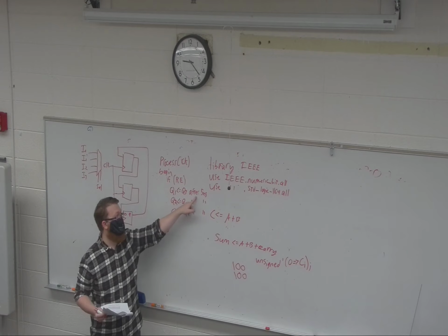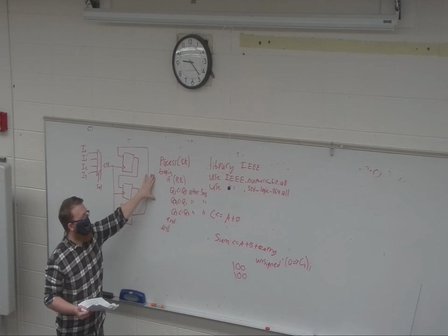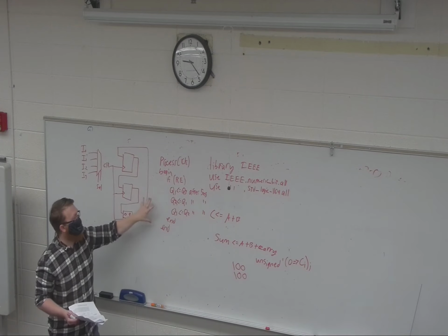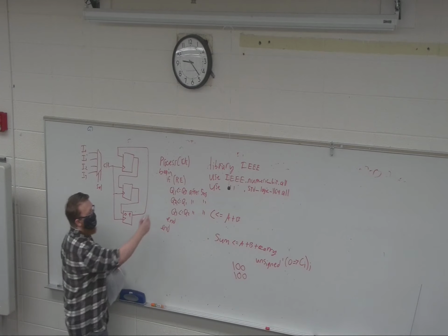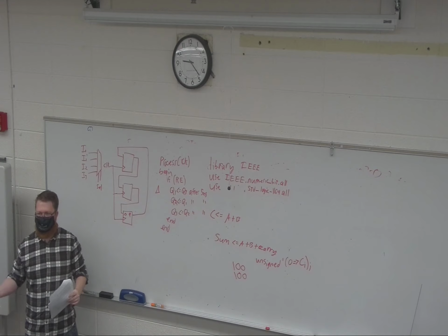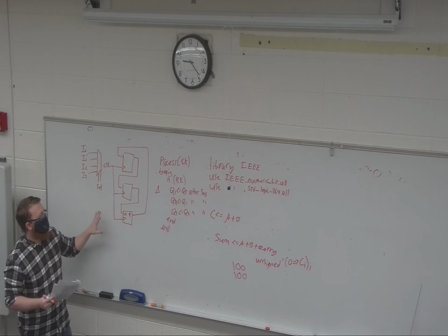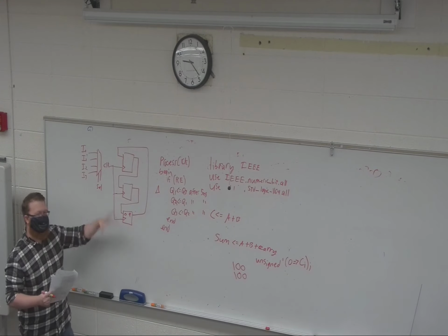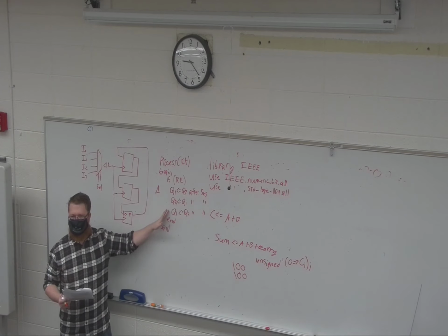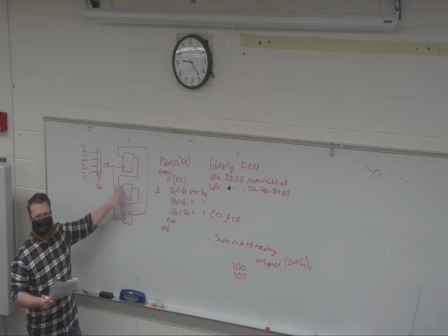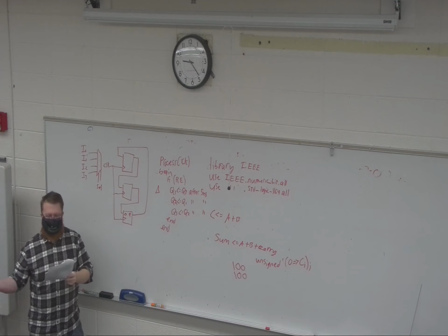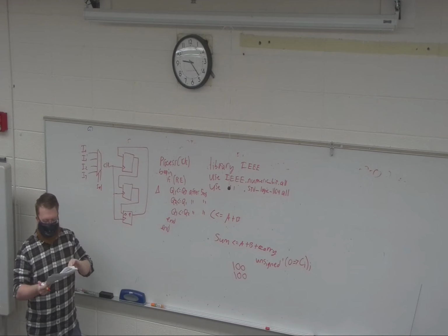It does not synthesize. But this is a great case where it is actually helpful to put it in, because when you simulate this, they're going to update after delta, which is the smallest time step that it can manage in the simulator, essentially. And it's going to look like just a cascade of data. If you add the 5 nanoseconds, it's going to simulate more like what's really going to happen. 5 nanoseconds is a reasonable amount of delay for that, and that can help your simulator look more like reality. And that's just something you'll grow to become familiar with.